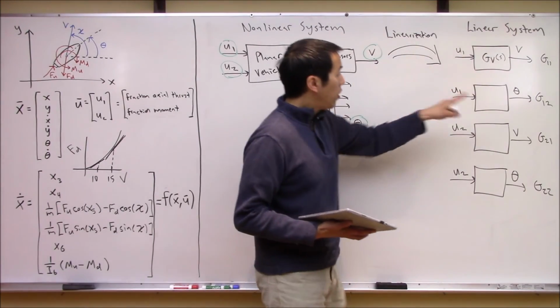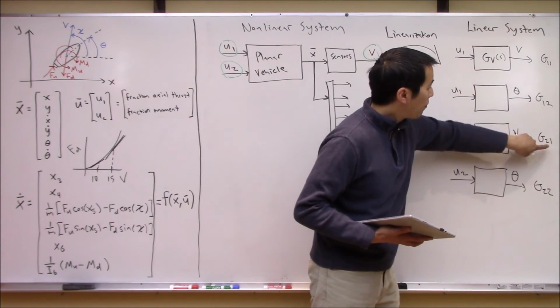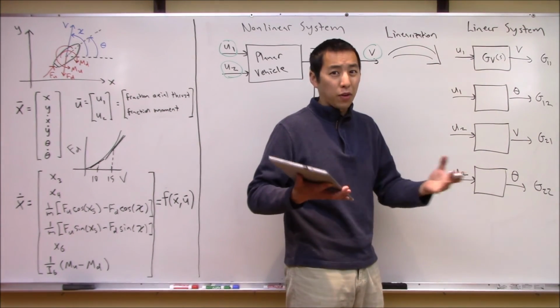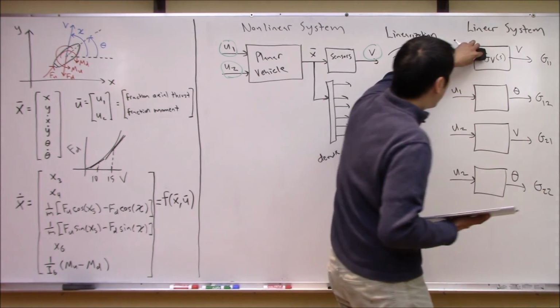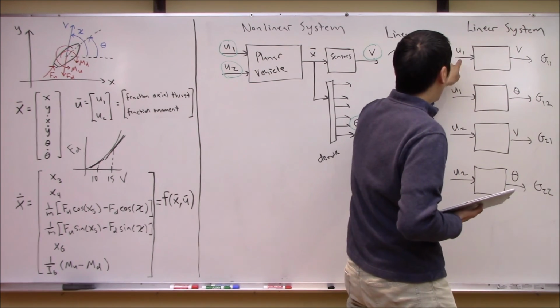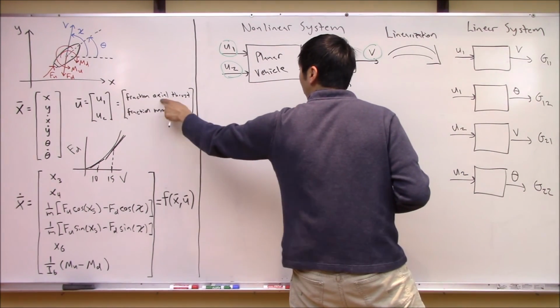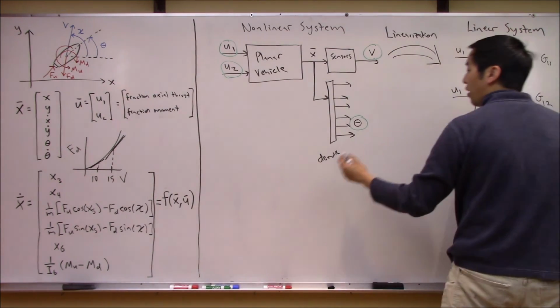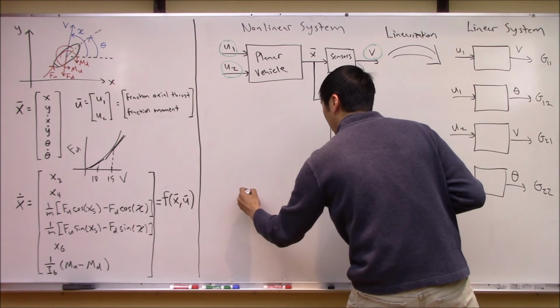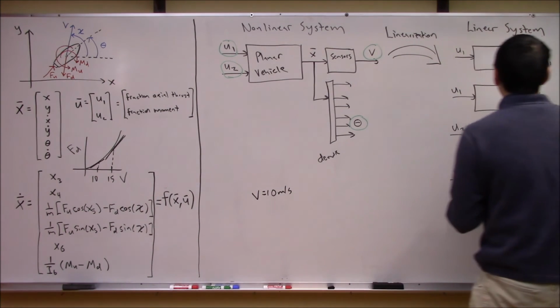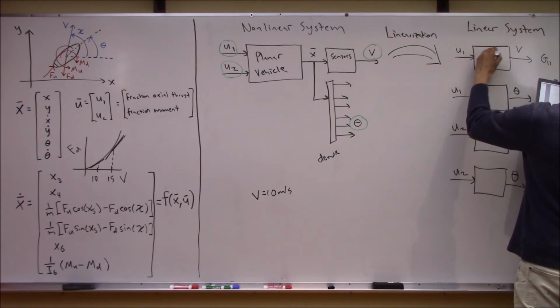All right, so we saw we have to be a little bit careful on the numbering here about which inputs and which outputs the system decides to call first, second, third, et cetera. But at the end of the day, the transfer function that we obtained between the axial thrust throttle input and velocity, at trim point 4, where the velocity was 10 meters per second, turned out to be 1 over s plus 0.05.